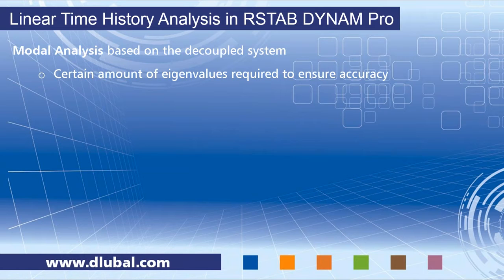The modal analysis in RSTAB is based on a decoupled system. So you really need a certain number of eigenvalues. This is required to ensure the accuracy. And how can you know whether or not you have enough eigenvalues? You can have a look at the effective modal mass factors. It's also important to compare the natural frequencies of your structure and the excitation frequency that you have.